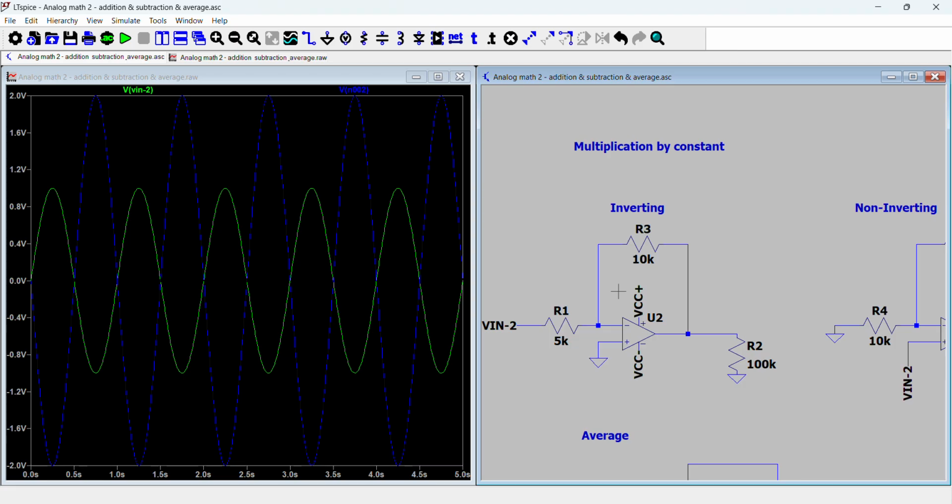The other thing is that we want to look at the input and output impedances of this inverting amplifier. And the input impedance is, even though the input impedance of the op-amp's terminals are basically infinity, in this config, because we have a resistor here, the input impedance is actually this resistor value. An input impedance can be determined by checking how much the current drawn into the circuit changes when we change the voltage of the supply. And in this case, if we increase the voltage, the current does change.